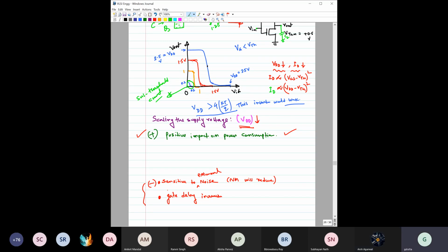No, see, maybe one quick example that I can give you right now. Suppose you are making a digital clock, the clock frequency you need would be very low. Sir, in the digital circuits or actual computer systems, the frequency is quite high, in the gigahertz range. That's right, in those applications it is not possible. But I'm saying this inverter would still show the VTC. It does not mean that the delay and clock frequency will all be aligned accordingly.